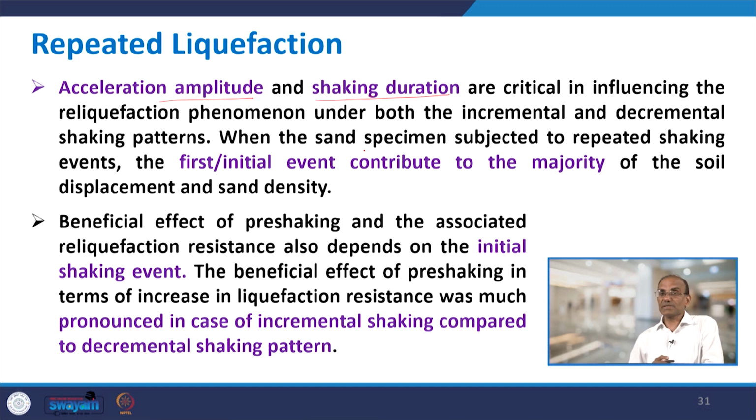When the sand specimen is subjected to repeated shaking events, the first initial event contributes to the majority of the soil displacement and sand density change, which you have seen, particularly in the decremental shaking pattern. 0.4 g is contributing a lot, and you get the beneficial effect of pre-shaking in case of incremental shaking, and the associated liquefaction also depends on the initial shaking event. The beneficial effect of pre-shaking in terms of increase in liquefaction resistance was much more pronounced in case of incremental shaking compared to decremental shaking pattern, which we have observed. So, this was the kind of conclusion obtained from the studies done on re-liquefaction.